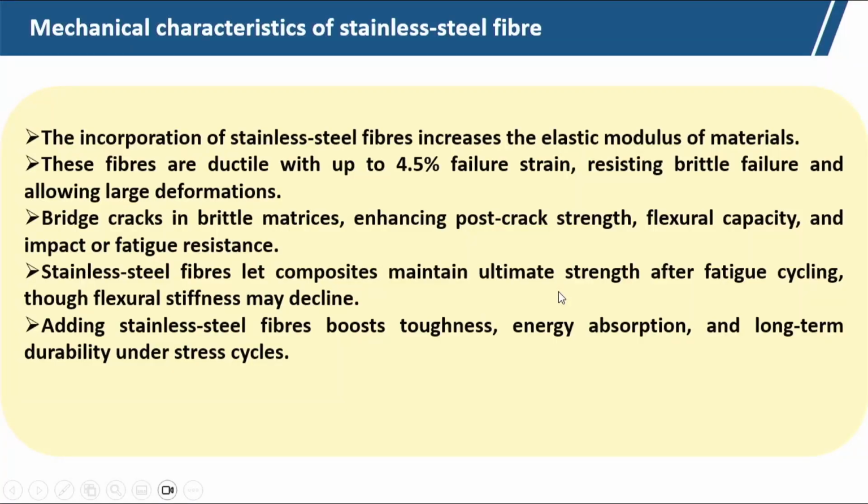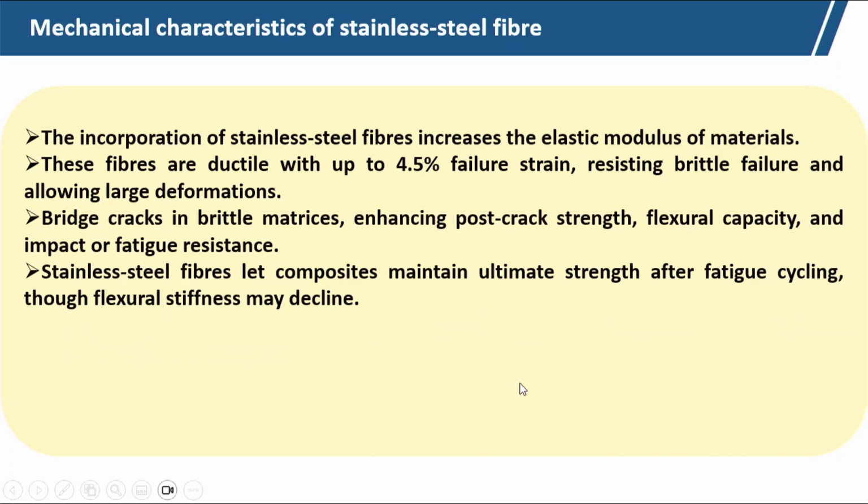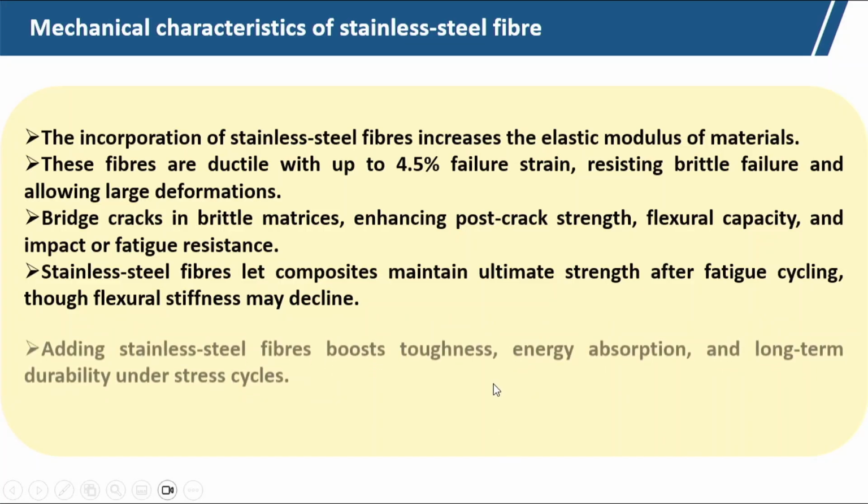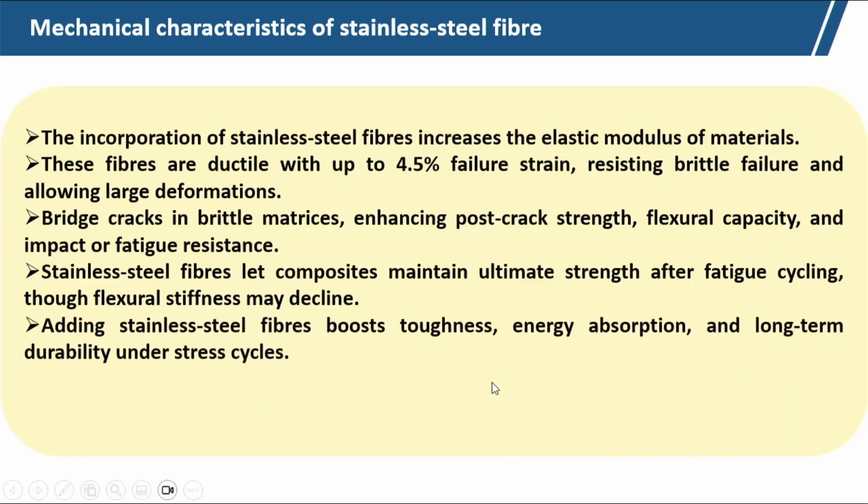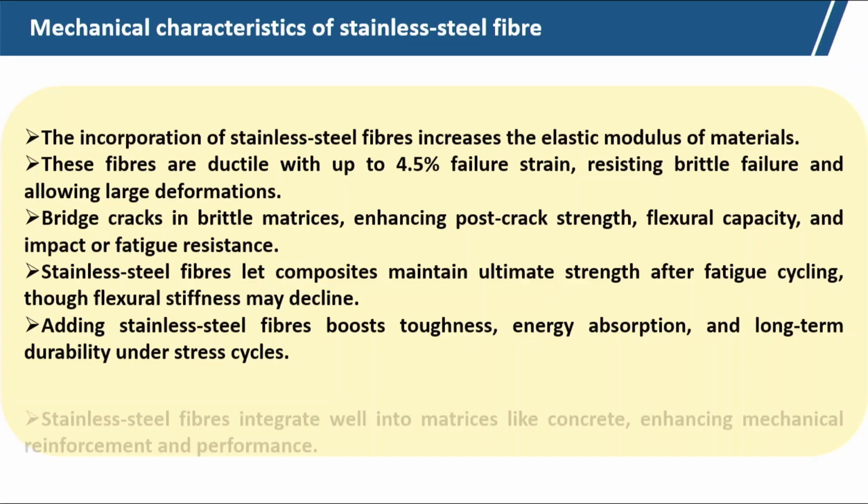So, adding stainless steel fiber boosts toughness, energy absorption, and long term durability under stress cycles. So, we can use this stainless steel fiber where long term repeated loading cases are there. In that case the stainless steel fibers will increase the toughness.